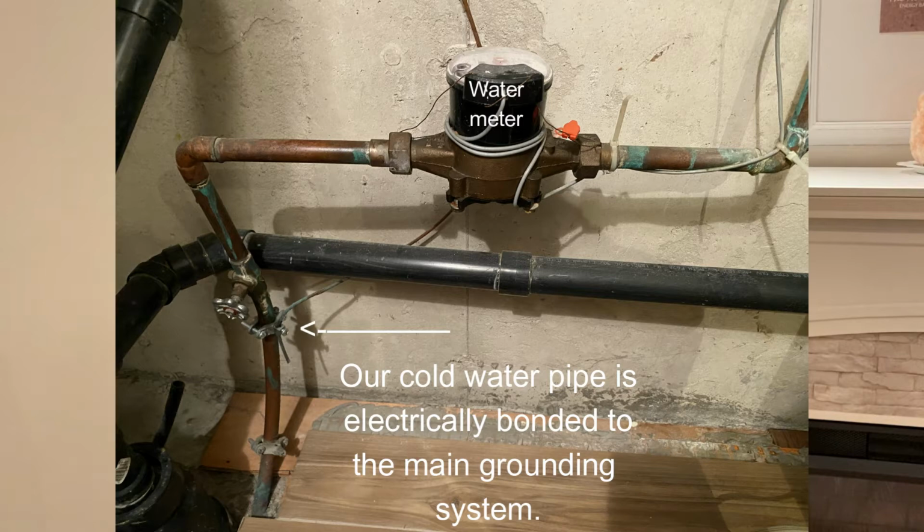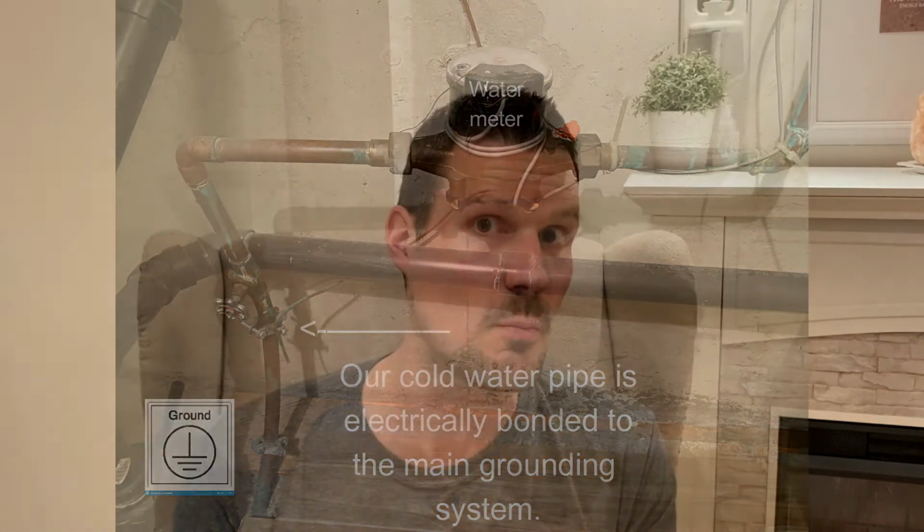That wire is making a connection up into your electrical panel. And in some cases, not all cases, we're using that cold water pipe as the main grounding electrode for the system that powers our home.